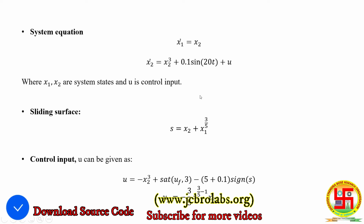For this video, we have taken an example of second order non-linear dynamics where system equation is x1 dot equals x2 and x2 dot is x2 cube plus 0.1 sine 20t plus u, where u is a control input and x1, x2 are system states that need to reach their respective equilibrium point. For designing sliding surface, we have taken x2 plus x1 raised to 3 by 5, and for calculating control input, we have taken minus 5 sin s as the u d part.